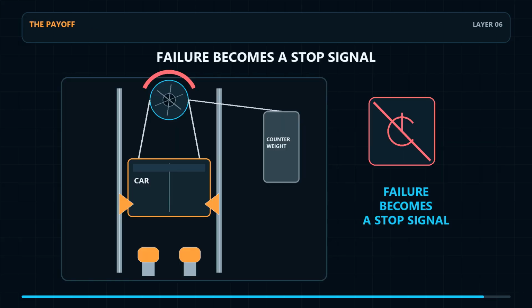So the hidden trick is not that elevators trust one component completely. The system is arranged so several failures create a stop command or a mechanical brake action. Power disappears, the first brake closes. Speed keeps rising, the governor and rail safeties take over. The transferable lesson is fail-safe direction. When energy or confidence disappears, move toward a safer state. That is engineering by layered consequences.